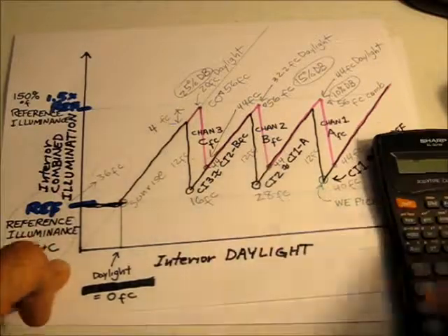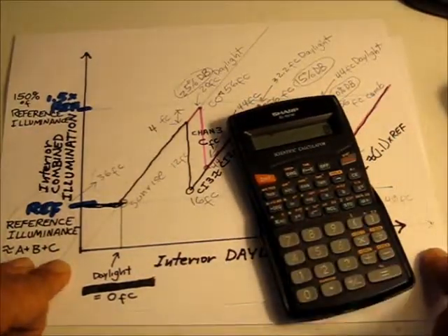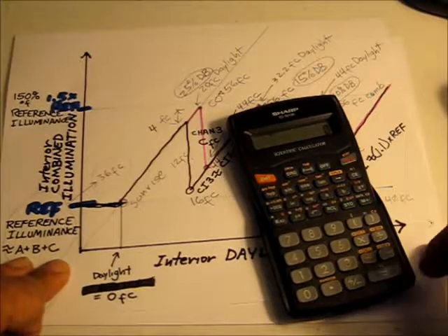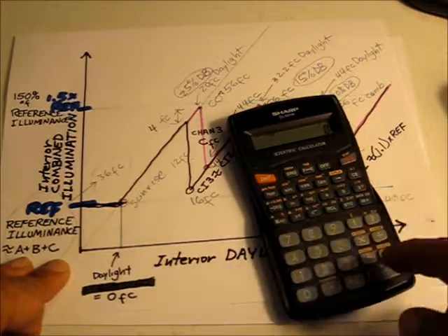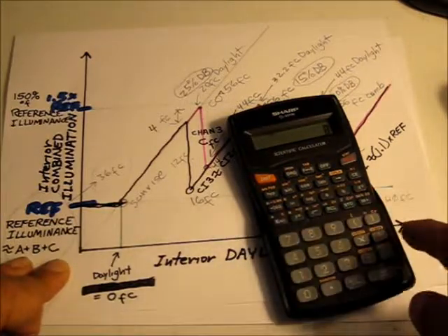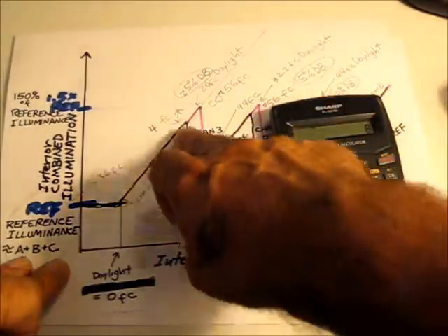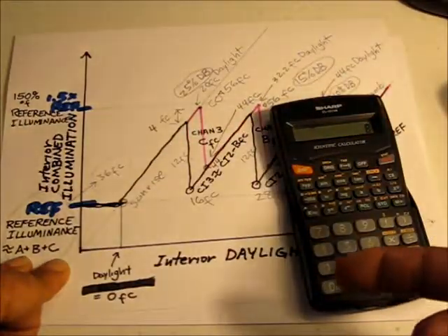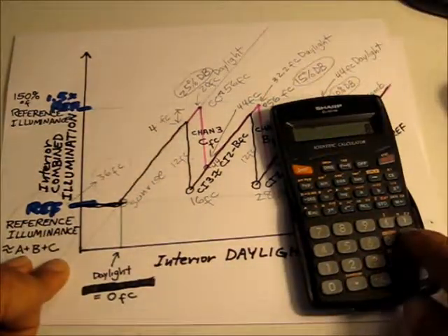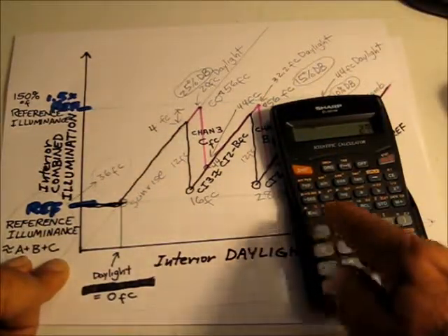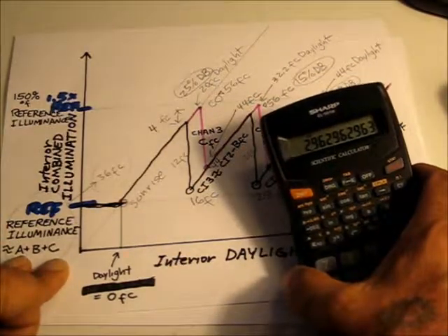Well, we'll use something close to the sensor ratio that we found in Module 3 for acceptance testing of 2.7. If the sensor is reporting that it's seeing 8 foot candles on one of the stages, that's its highest stage that's hitting it, we divide by the sensor ratio of 2.7 and we come up with 2.96.